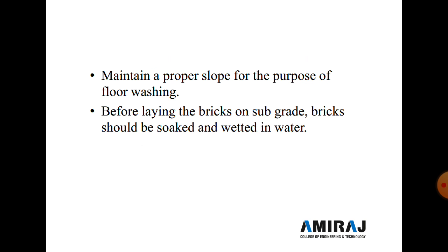At the time of making the subgrade, it is essential to maintain a proper slope for the purpose of floor washing. Before laying the brick on the subgrade, bricks should be soaked or wetted with water so that the water from the thick mortar bed will not be absorbed by the brick, and in such a way the strength of the mortar will not be affected.